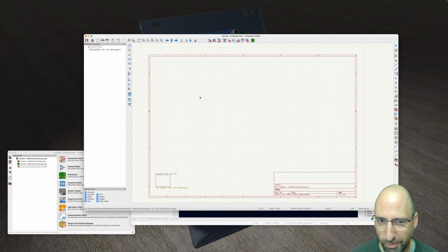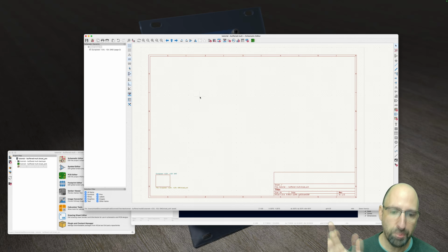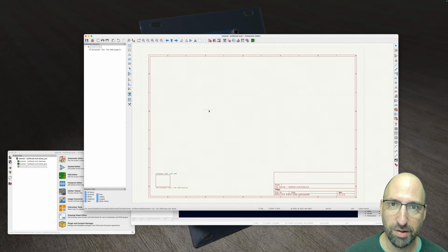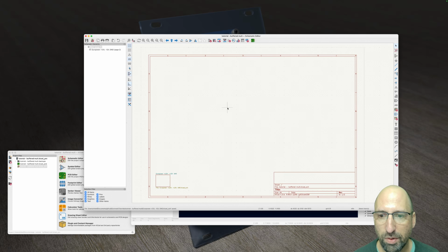And the point of buffering is we don't want to affect the input signal by having it go out to different modules, because that would actually change the signal that's going into all the different modules, depending on how they are wired up to use it, right?